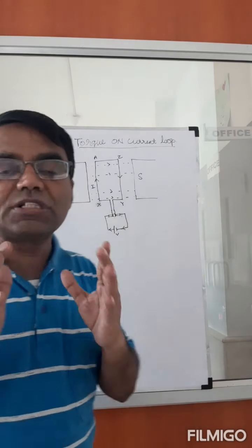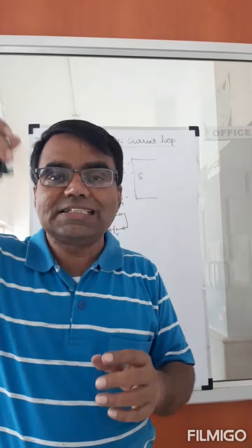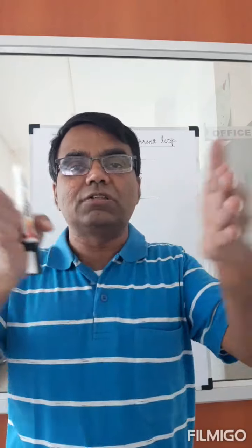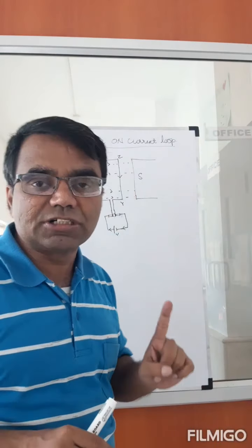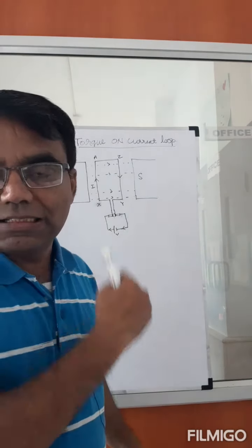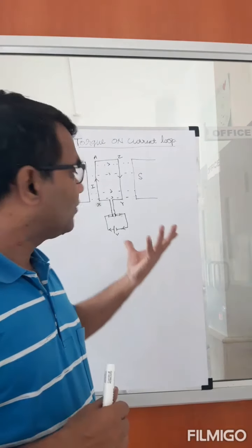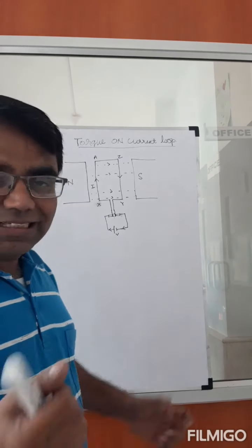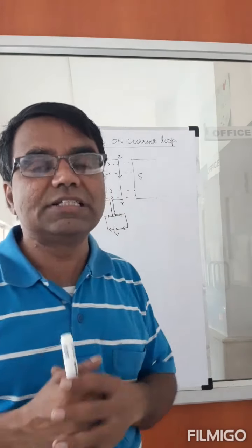If you don't have a slip ring, then the direction of the current doesn't change. If the direction of the current doesn't change, then you will have oscillation, not rotation. And that is the function that the slip ring does in this arrangement. Okay? So this you already know from your 10th standard, or most of you would know it.